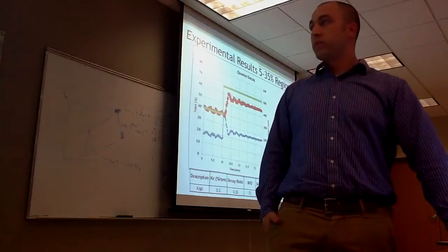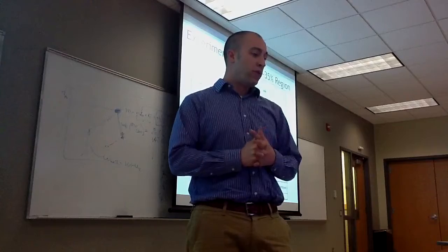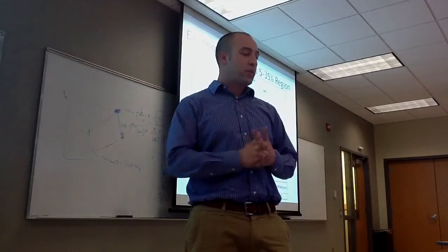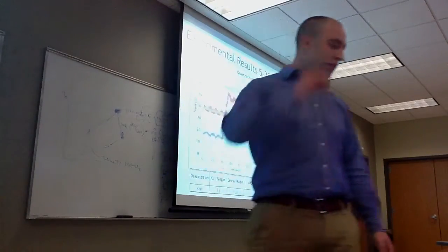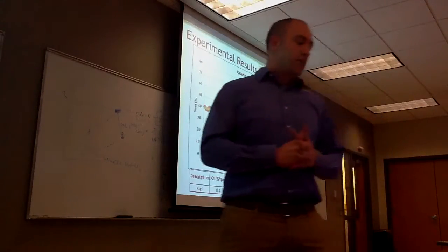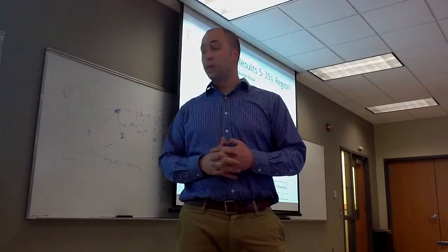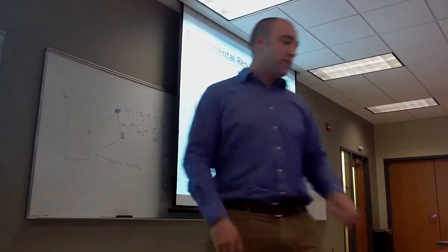This is the quarter decay, which I found to be 0.1 because I found the ultimate gain first, and the equation is ultimate gain divided by 2. So it's 0.1, the decay ratio is 0.26. It's oscillatory, has a settling time of 1 second, and an offset of 70 RPMs.